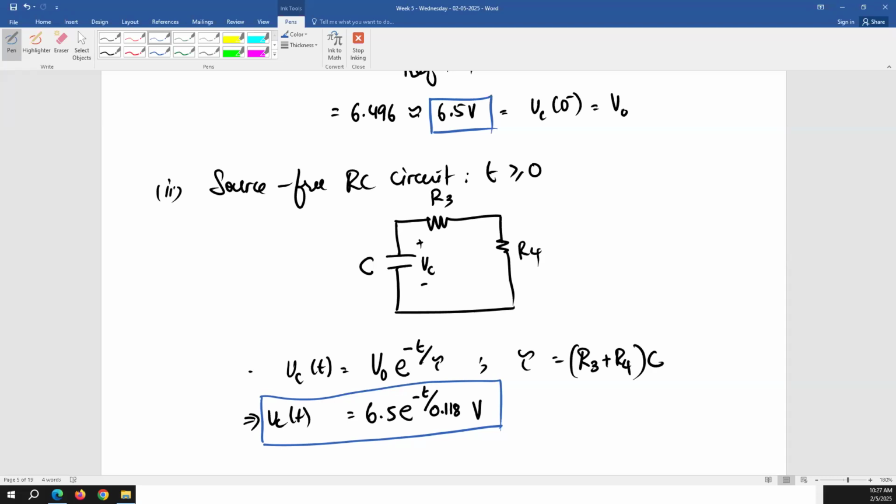So basically, what you were doing, you were creating an RC circuit like this, because you had the load connected, which was a resistor, and you were connecting a capacitor in parallel to that. Now, the value of capacitor that you're supposed to choose is such that the time constant of the circuit RC becomes large enough, such that when the next waveform is arriving, the capacitor is still not discharged much. So if you make the time constant larger than the time period of the pulsating waveform, quite large, I would say,